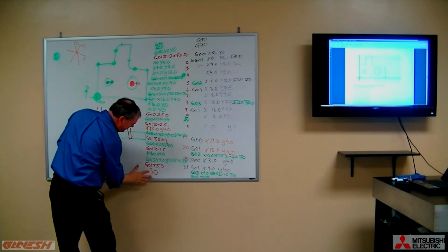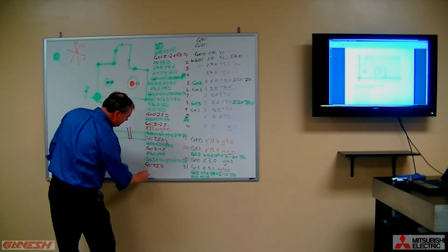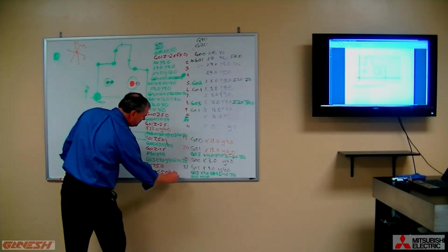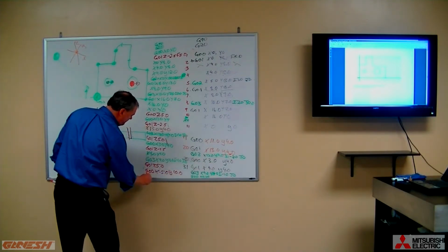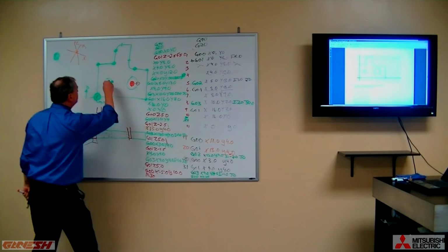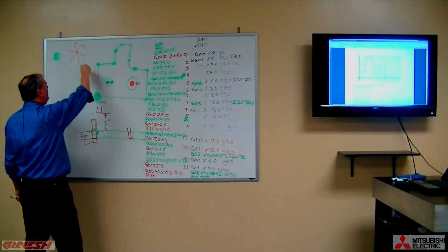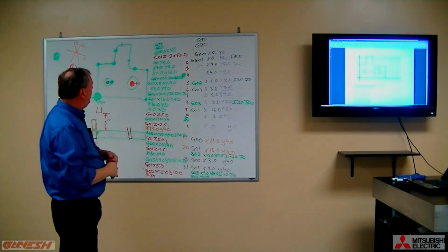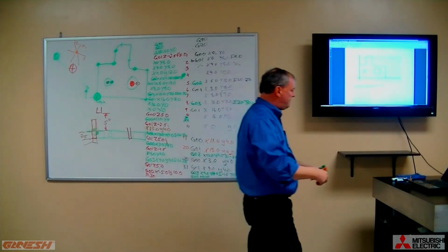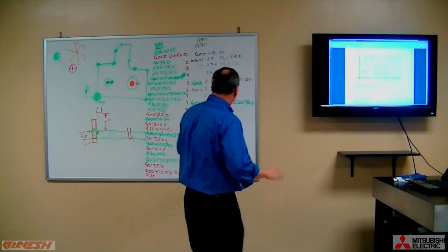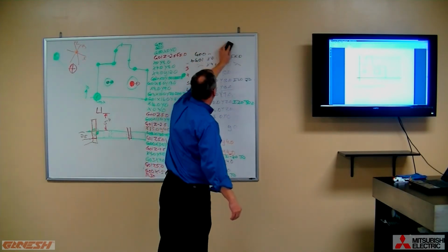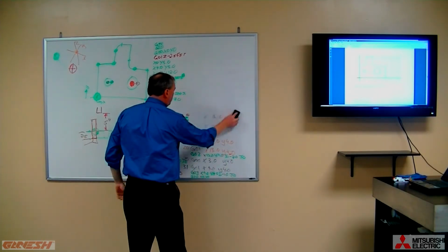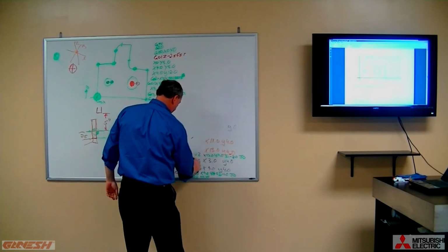So let's do that as one last rapid move. So I can now say G00. Let's go to X minus 5 inches, Y plus 10 inches, and then do the M30. So what that does is it has the cutter sitting here up in the air. It's going to move over to this location and then end the program. And now we have the makings of a proper NC program, almost. There's still things missing, but you see we're increasing the accuracy of our program, that it's going to be doing real stuff as we go here.